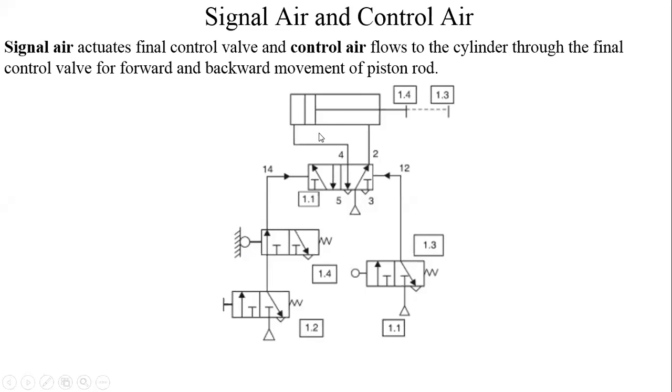So in the circuit diagram that you have drawn at present, what it suggests is the compressed air supply will come to this port once the push button is pressed, and then it will go through this port. It will go here. It will activate this side. It will go to the full bore side of the double acting cylinder. So this particular roller lever valve is activated right now.